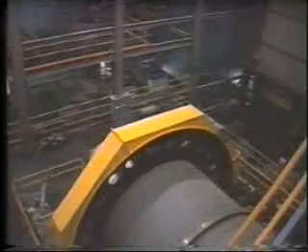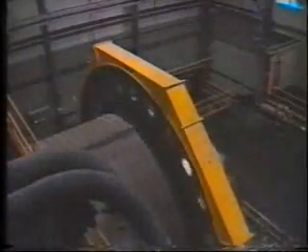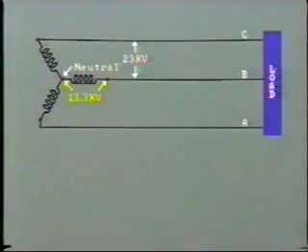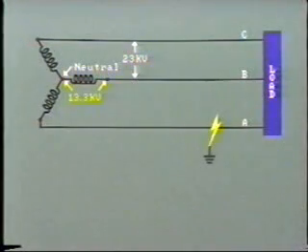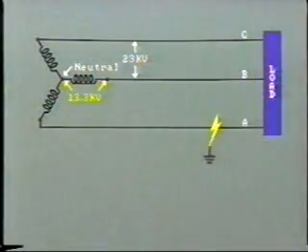Well, one reason could be to ensure continuity of supply. For example, an industrial installation which must have minimum outage. In this case, if a ground does occur on one part of the system, no tripping will occur and power supply will continue. The three phases will continue to feed the load and retain the normal phase relationships. However, this method presents several possible hazards.